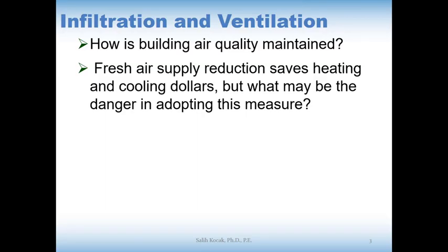However, what may be the danger in adopting this measure? If we adopt this, which means reducing the fresh air supply, it may cause health problems because of the quality of the air inside the building, even though it is conditioned air, heated or cooled, it is not fresh air anymore.